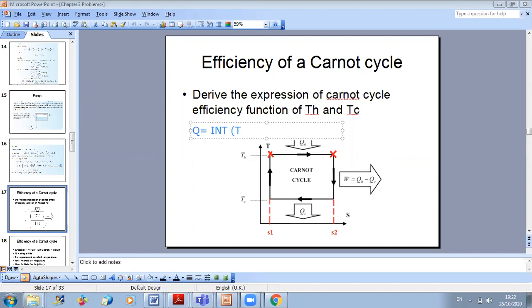And the total heat is always integral TdS in case of one phase or a cycle. This is why for the whole cycle, total Q equals total W equals total integral TdS. But if I take just one phase, for example this phase where I have heating, then I can only say that in this phase Q is integral TdS and not work, okay? So pay attention to this information.